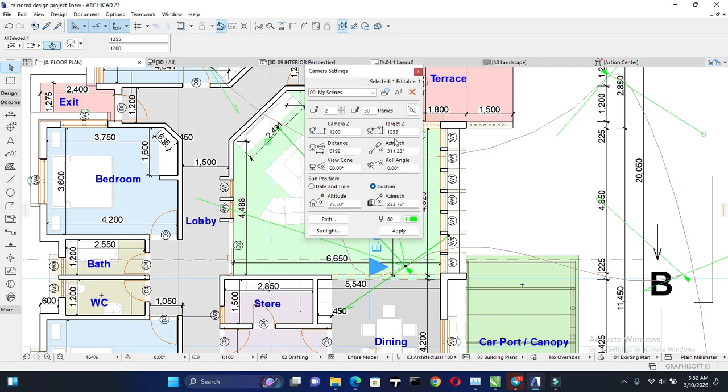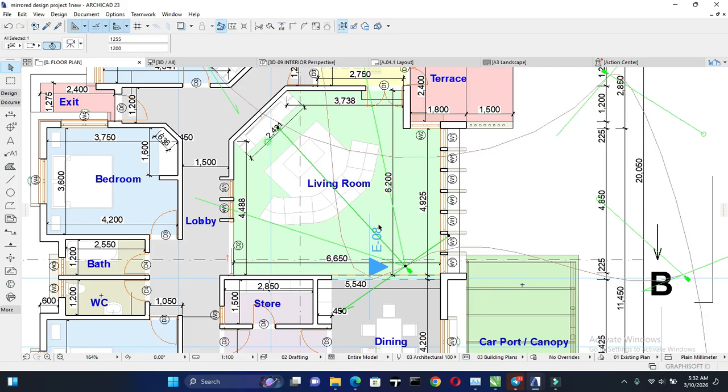And I think I should show how to place your camera, because I don't think I have done that in any of our tutorial sessions before. So just go to your more and you see camera tool at the end. That's one of the last options there. When you click on that camera, you come to anywhere you want to place a camera. Let's say I want to view this room, so my camera position is here for the meantime. I click on that position and then tell it which distance I want to view it from. So I have a camera that is viewing this bedroom from here, here and here.